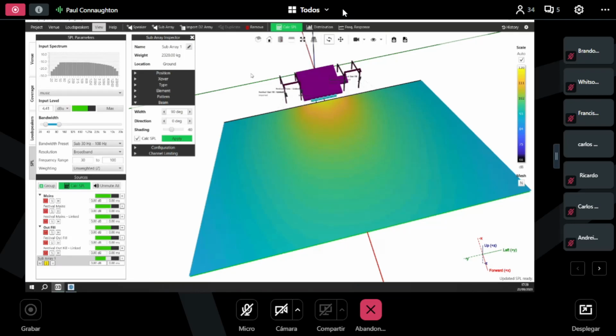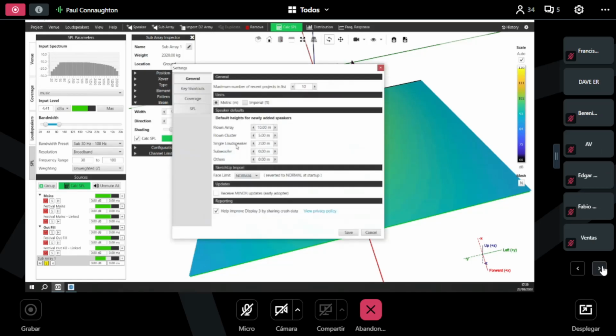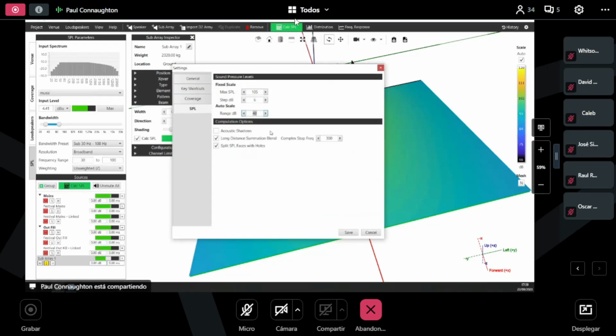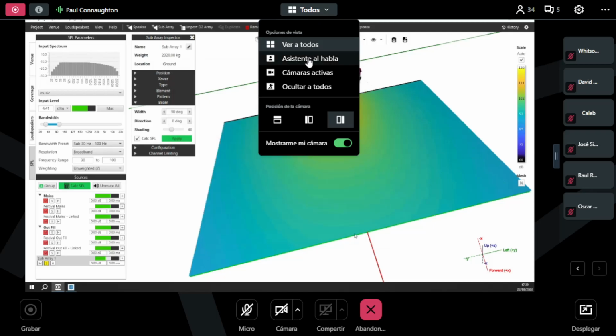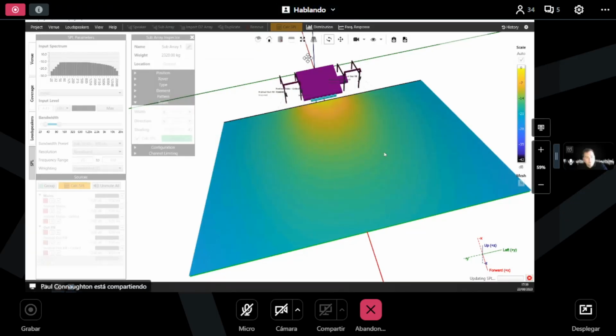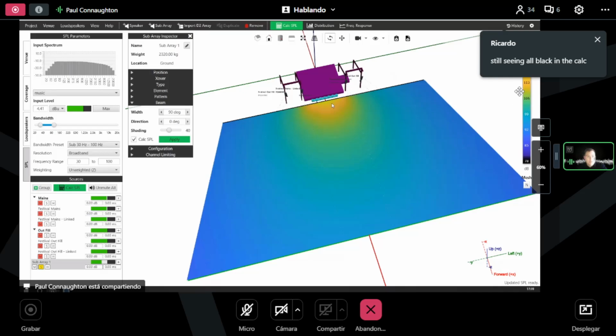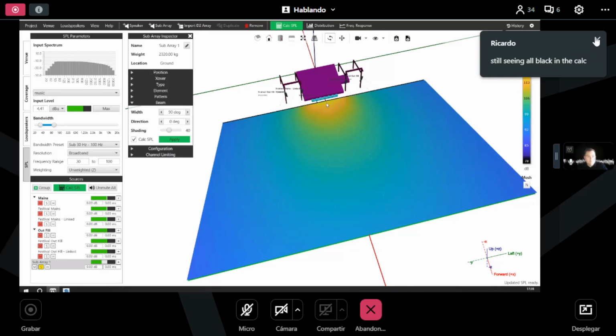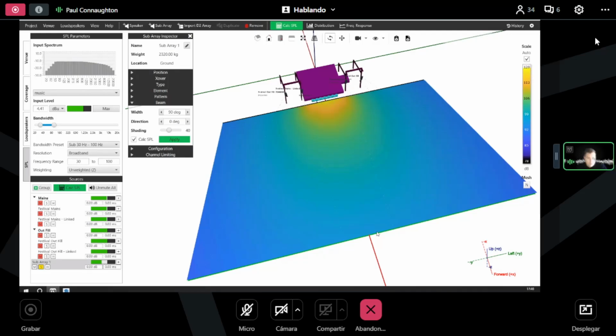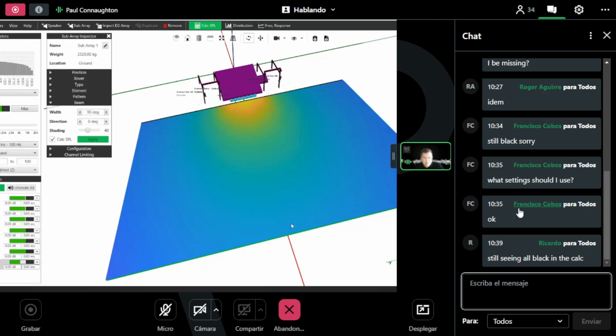And yeah, really good. If you really want to get into fine detail and see what these arrays are doing, what the subs are doing, you can change these values and just decrease your range value, and you'll start to see more information, what's physically happening here. So look here, we've got 120 dB right in the near field, 2 meters away from the array, as you would expect, and then coming through all the way into the far field, which is 80 meters back, we're probably looking anything from 92 to 95 dB at the back here.